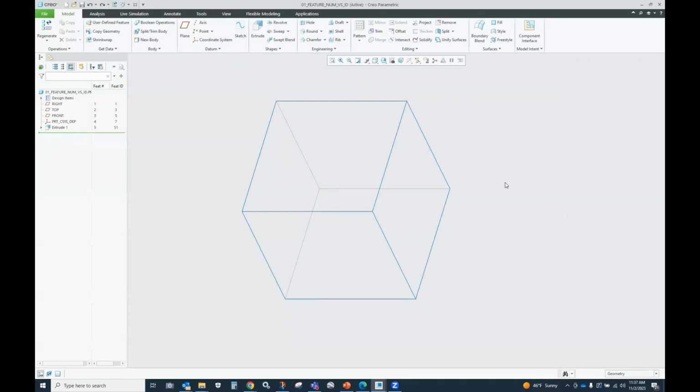Right, because I'm still using the intent selection that's built in, right? So in this case, I probably have three, there might be more, but there's three intent selections, right? There's one there in the back, right? That's ID 76. There's one in the front, which is ID 75. And then there's this one, which was ID 77. I guess my question is, how is it determining those exist? Because those are sharp edges created in that extrusion, right?